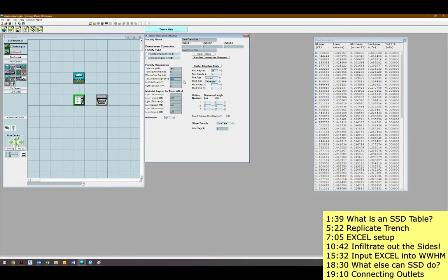I'm going to have a top and bottom slope 0.01. I'm going to make these side slopes 0, which is more typical for an infiltration trench. I'm going to make this layer 1. I'm going to make this 4. I'm going to use 0.33 is fine. Actually, I can go up to 0.4, so I'll do that. I'm going to delete these other ones.